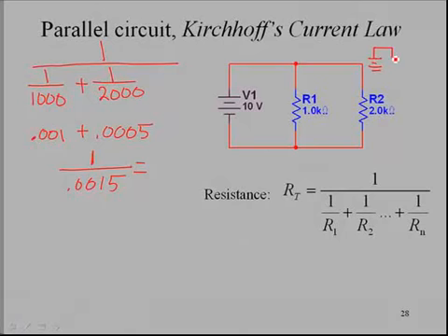And so if we were to redraw our circuit here, if we said here's our little power supply, and if we put the resistance over here, the equivalent resistance is 666.66 ohms, and then our applied voltage is 10 volts. And so that gives us our parallel resistance. Now remember, that is the resistance that is felt when 10 volts is applied to these two components. That is the parallel resistance. Now something your book doesn't go into, and my real concern is that you be able to use this formula.